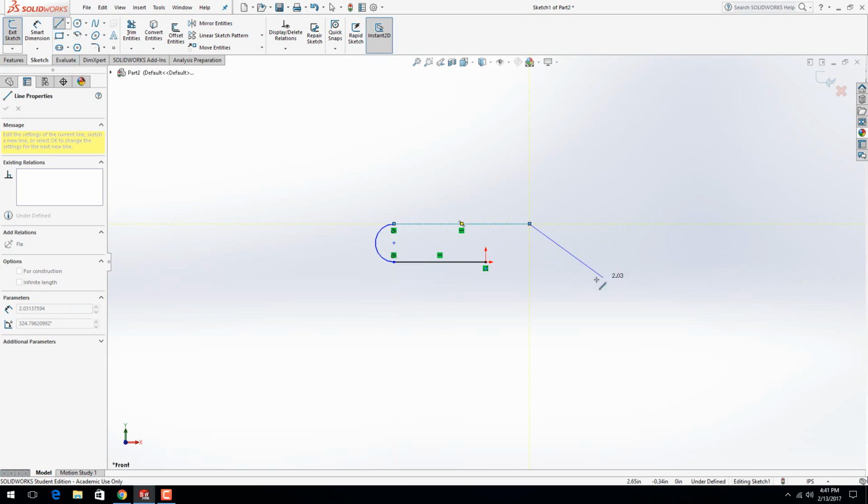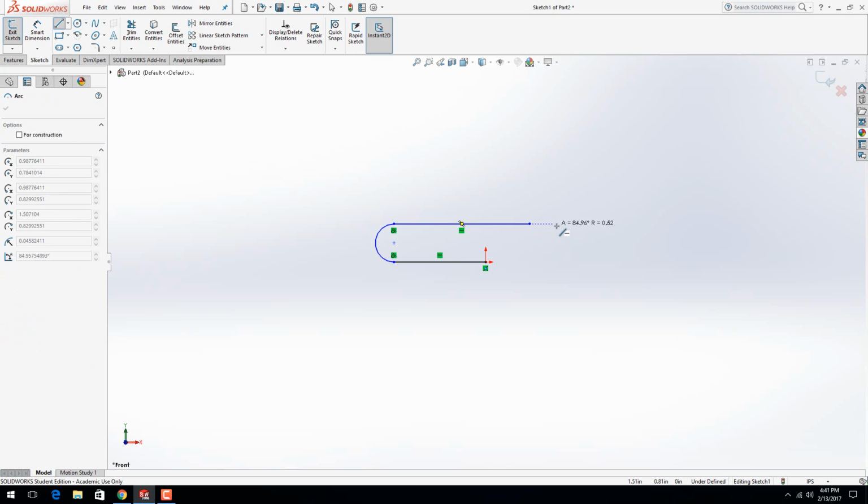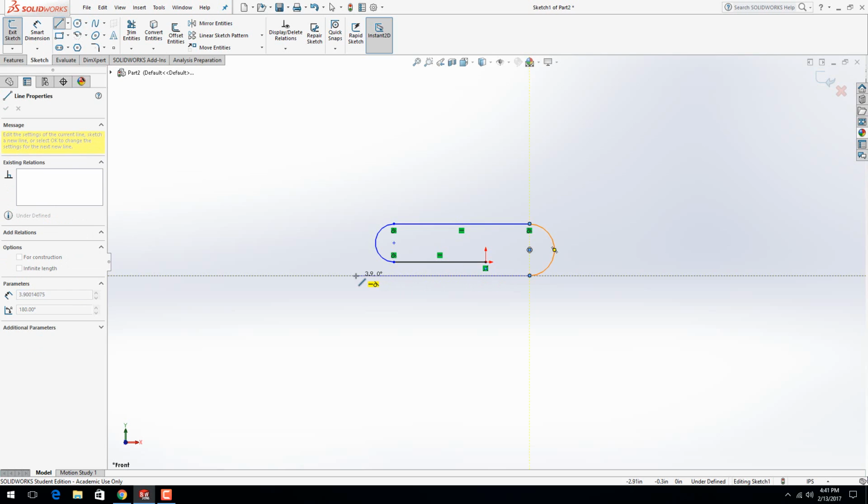Now I'm going to do the same trick. Chain away and then move back. Just hover over it and then move to the right and down. And notice I'm getting A is equal to 180 degrees. Make sure you get that. I should have told you that the last one too. But go ahead and click. Drag across, and this is going to go maybe 4 inches. And click, and then do the same thing again.